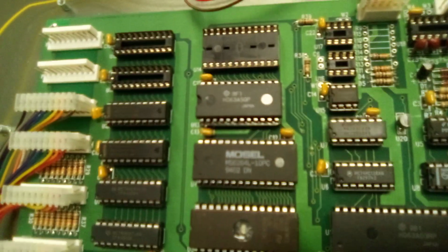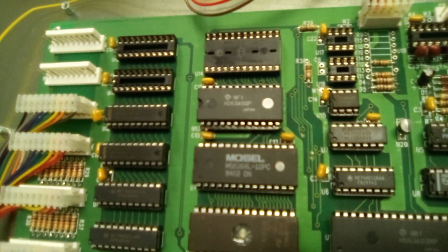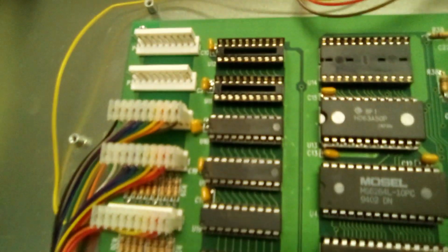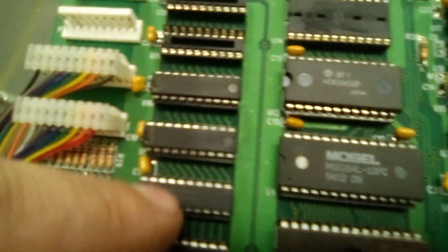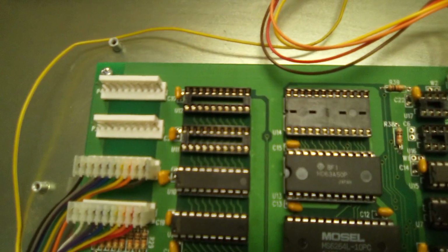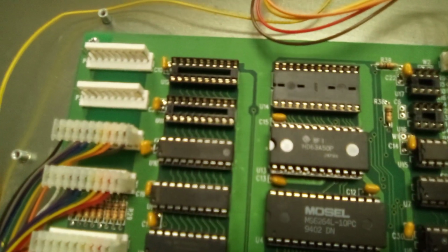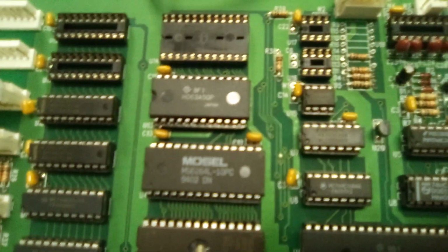But so far I've gotten out almost all the select lines for everything. Well, U9, U19, U12, which doesn't exist. U11 probably has another select line too. I'm guessing that's probably pin 12 of the 74LS138. But that's about it. Here's the thing again. Not too descriptive, but it's a start.